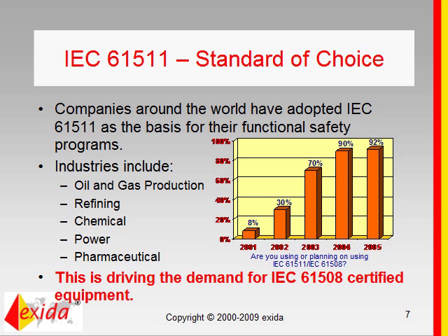It doesn't really tell you what that means, except there is a letter from OSHA to ISA indicating that ISA 84.01 is a good example of good engineering practices. So though 61511 may be mandatory over in Europe, it's optional here in the US. You need to do good engineering practices, but this is an example of good engineering practices.